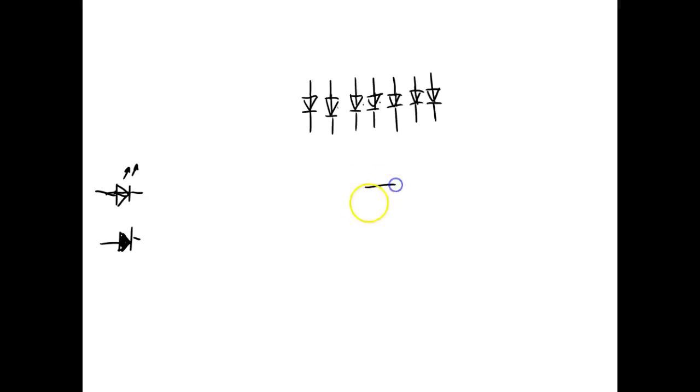So we have a 7-segment display. I'm just going to draw it roughly like this. What do we call this segment right there? Yeah, that's the A segment. That's the name of that segment, right? You understand? And then we just do what? B, C, D, E, F, and then G would be in the middle. And then we have one little dot over here, and they named this DP. I wonder what DP stands for. Decimal point, right? And you can buy them with left-hand decimal points. You can buy them with right-hand decimal points. You can buy them with colons too.